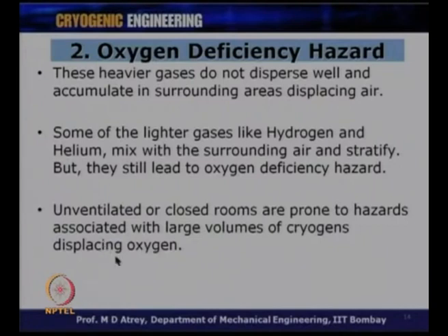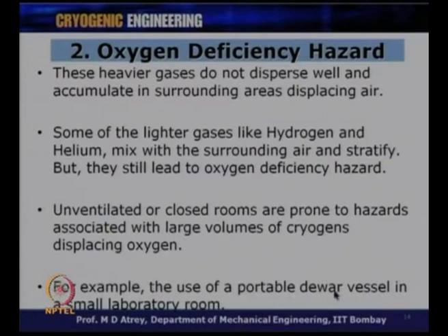So, as I said, such conditions can occur when you have unventilated or closed rooms where there is no air circulation, and therefore, this can lead to an oxygen deficient atmosphere, which can lead to asphyxiation. Therefore, we should have very good ventilation and we should have all open rooms. You should have windows and doors all open, and therefore, air circulation will be the best over there. For example, the use of a portable dewar vessel in a small laboratory room can lead to such cases, because